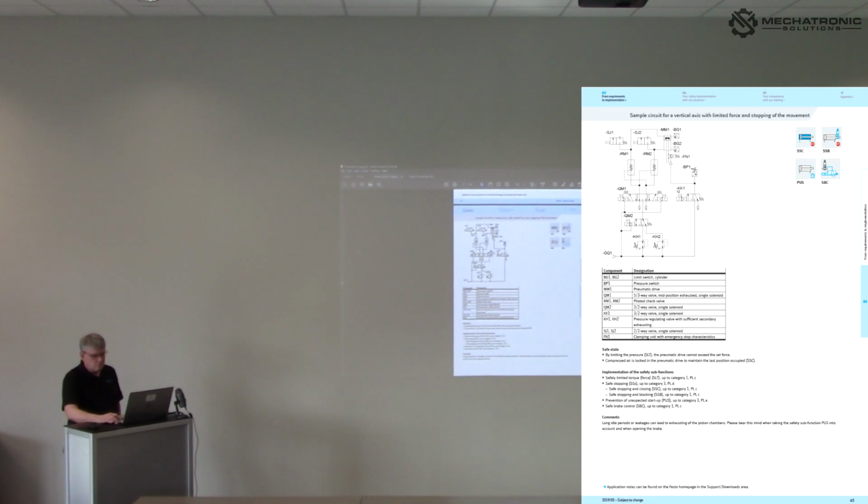With pilot operated check valves like this one, if somebody got injured and they see the PO checks in there trapping air, you probably have some trouble, because you've got stored potential energy between the valve and the actuator. When you hit your dump valve, you better exhaust everything.